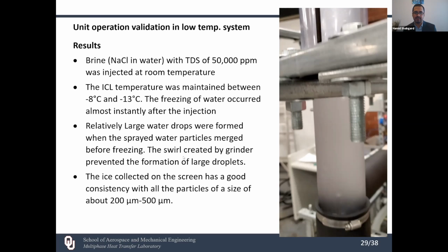The main motive for looking into freezing was potentially lower energy cost. As I said, for per unit mass of water, you need 1/7 of the energy to freeze than to evaporate. But there is a very important technical problem with evaporating. For produced water, as somebody else also mentioned, there is a lot of hydrocarbon in the water, oils, all sorts of hydrocarbons that evaporate before the water evaporates. So when you evaporate, all these hydrocarbons would be in your vapor.